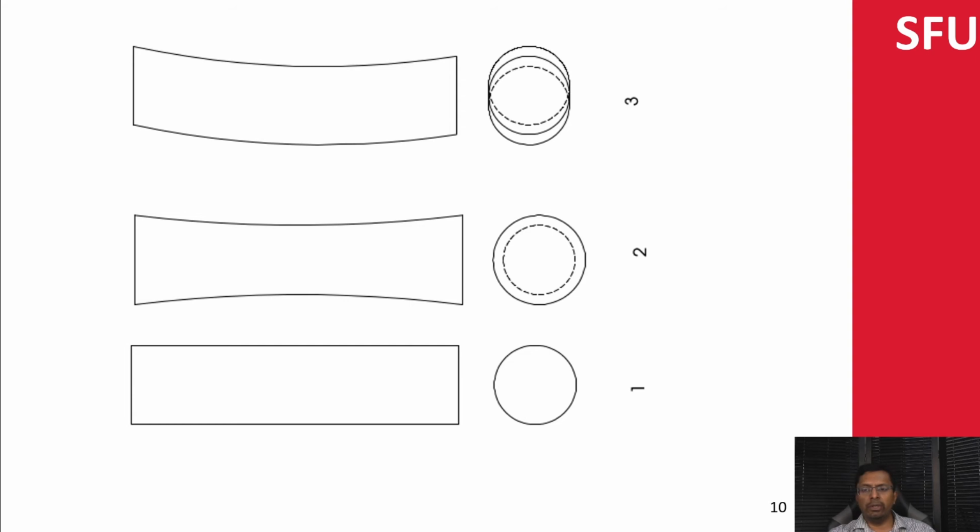So what you're going to be doing is, I'm telling you that I had somebody manufacture all of these parts. All of these are referring to the same basic size and the dimensional tolerance. So what you're going to do is work out the potential tolerance here. You're going to look at the variation in the size cross section, which will give you dimensional tolerance, and also the variation in the center axis, which will give you geometric or the true positional tolerance. So assuming all of these are located at a particular point.